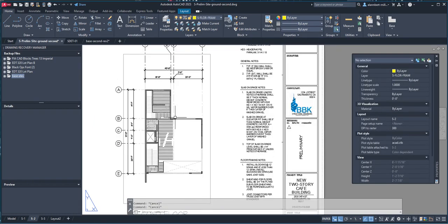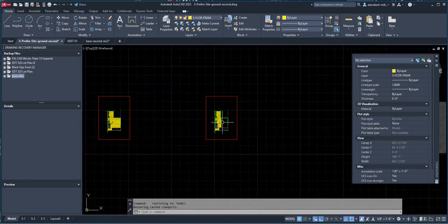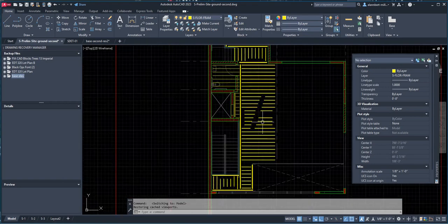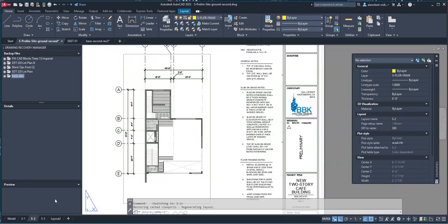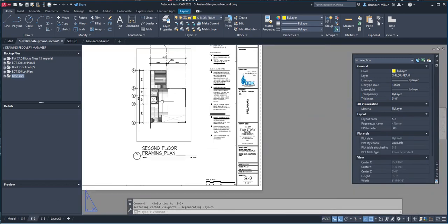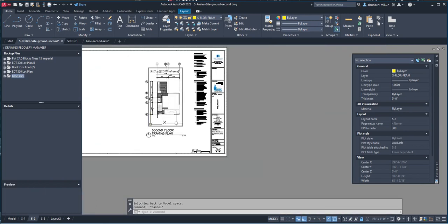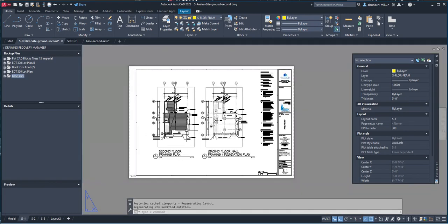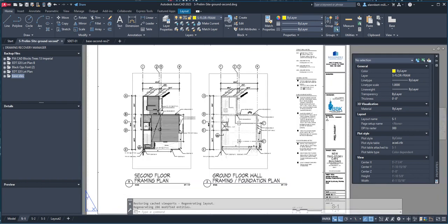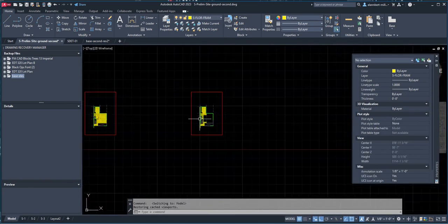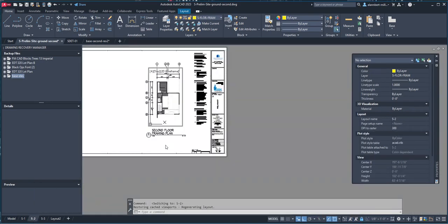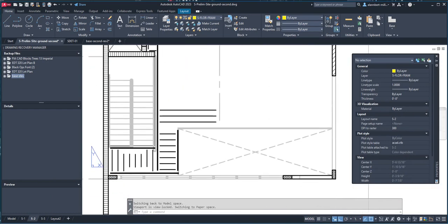There you go. Okay, so you're back there, and just adjust this viewport so we don't see any extraneous things. All right, so now you can see I deleted this because it's this part of the viewport. Okay, so we can delete again all of these over here, and when you go back to S2, you see that all this is deleted. So it's much safer to do this and keep your S1. If you inspect S1, S1 should not be affected by it because S1 is pointing to a different copy of the floor plan. S1 is pointing to this, while S2 is pointing to this. Okay, so much safer to do this in S2 so you won't make any mistake.